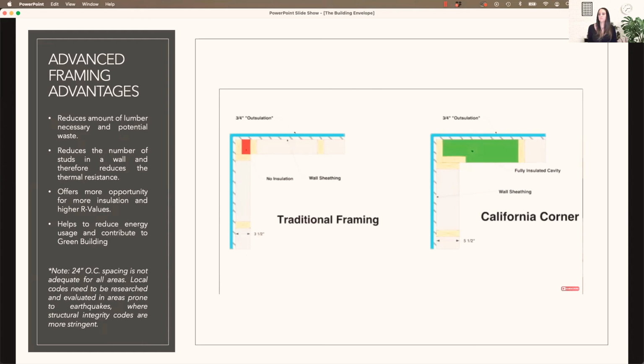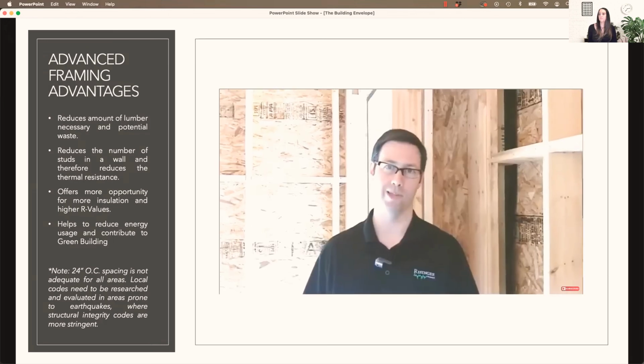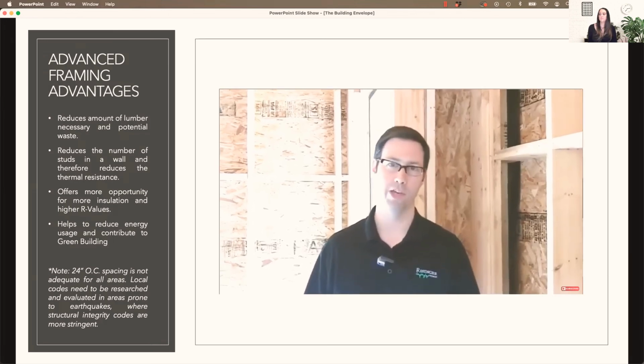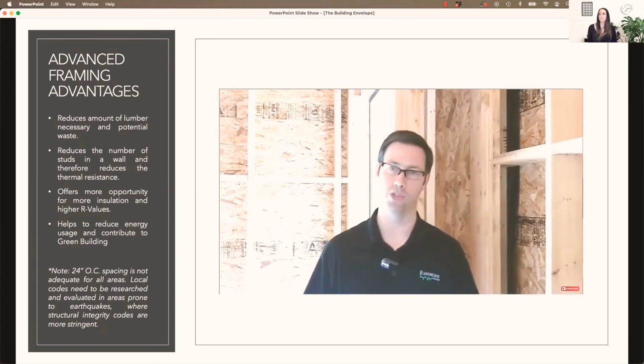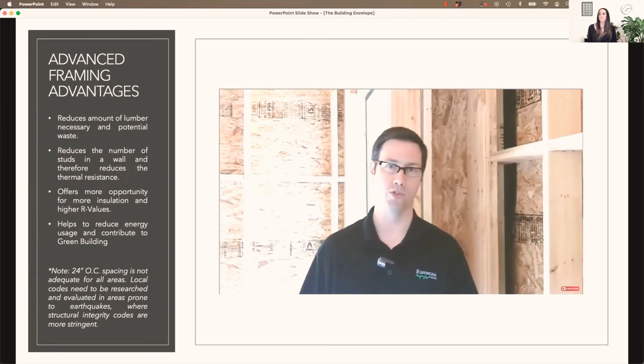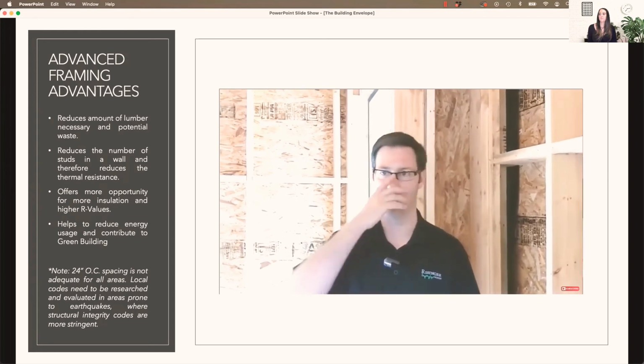And last, when we install drywall, I really prefer to use 5/8 inch thick drywall instead of 1/2 inch drywall. A lot of advantages to that. But the big one is when we go to advanced framing on 24-inch centers, it's a much stiffer product. We typically do smooth wall in all our houses, so we have very smooth drywall.